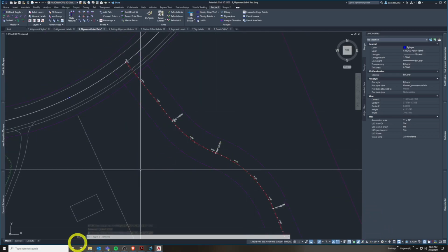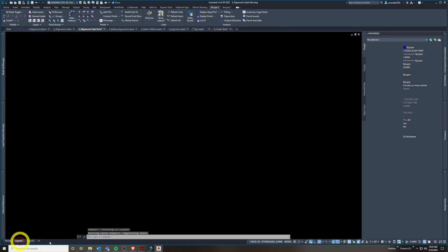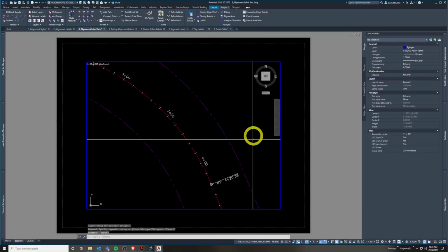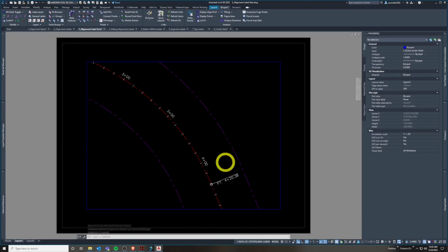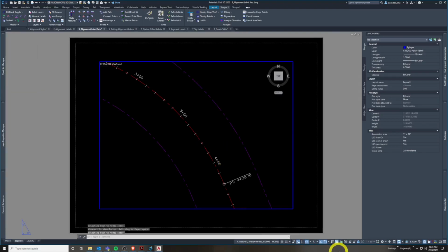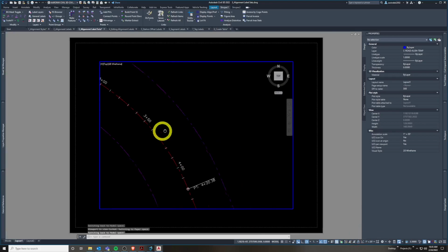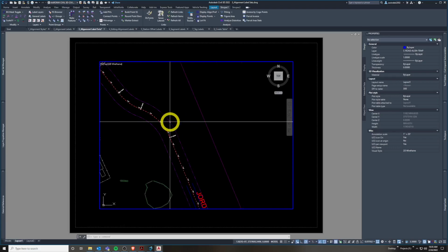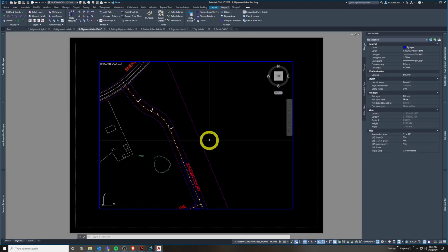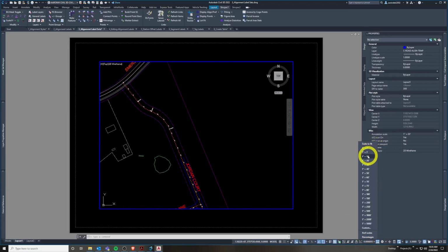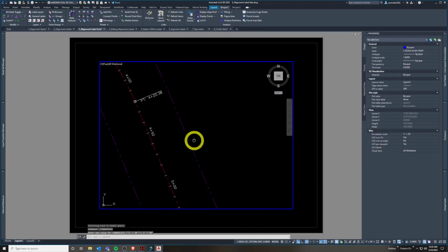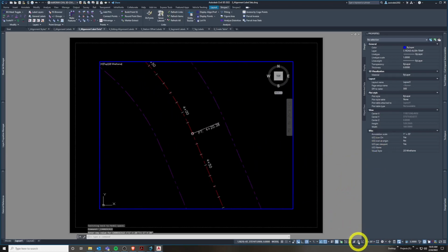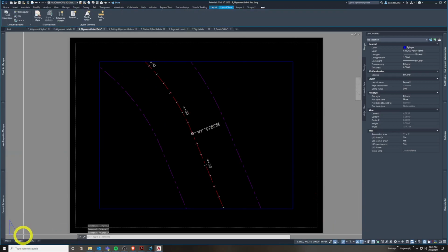That won't be reflected in this viewport. So say this viewport, this stays the same. This is 1 to 20 no matter what I do. I'm going to lock it right here. I'm going to lock the viewport. That means I can't zoom in and out, pan around. But if I unlock it, I totally can, by accident even. Zoom in and out with my roll mouse or side to side. Let's go back to 1 to 20, and let's lock it.